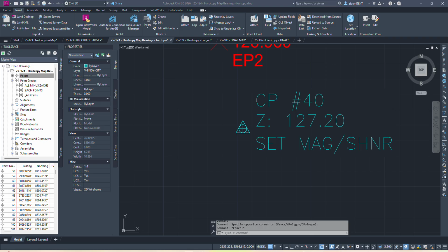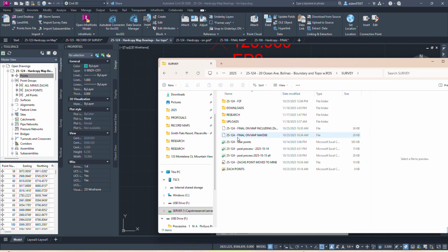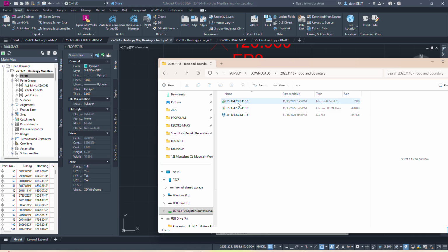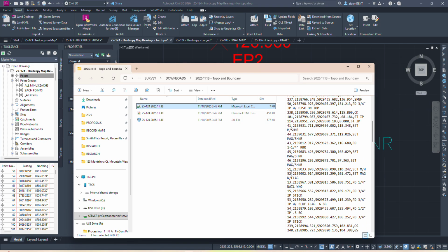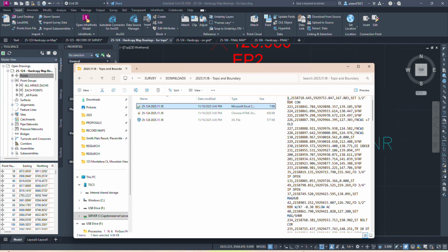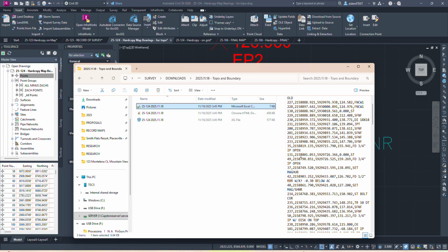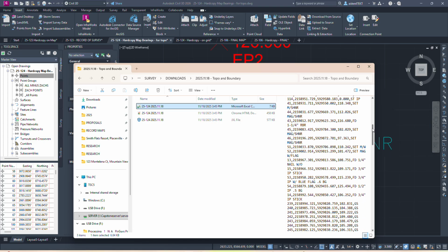So here's what I'm gonna do. I am going to look at my points here, downloads, and I'm gonna look at what's the last point, what's my control point numbers I got here, because those are really the only ones that are overwriting, because it has one right here, and one is a previous one, so the software doesn't like two of the same point numbers. It'll force you to renumber them. So that's what's going on here. Some of these are the same numbers.